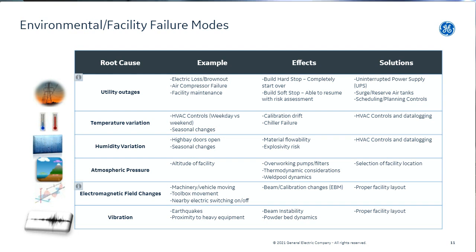And the machine ran great from morning until about 5 p.m. The increased temperatures caused our chiller to work harder than it was intended to. They're designed to be in an air-conditioned environment. The chiller would trip out high-pressure alarms and stop the build. And it's kind of frustrating how it usually happened after you had gone home for the day and everything looked like it was running smooth. So temperature controls are absolutely critical to keeping these machines running, and that's also covered in the installation manual for all the machines. That was us pushing the process limits.